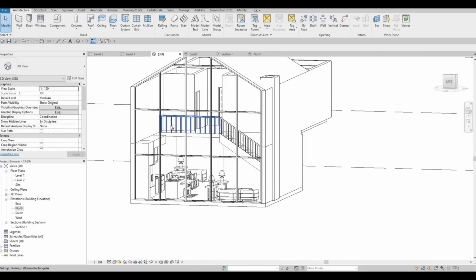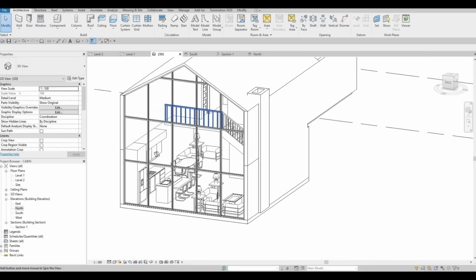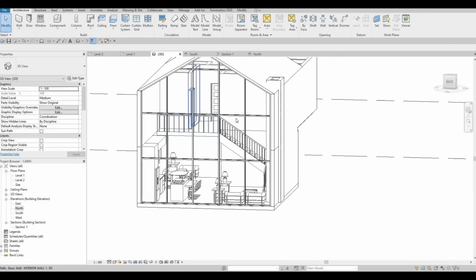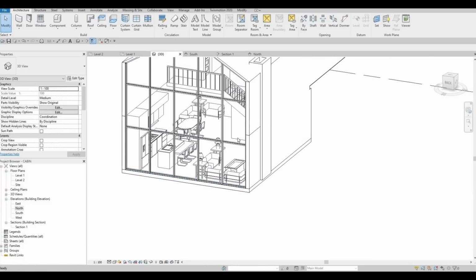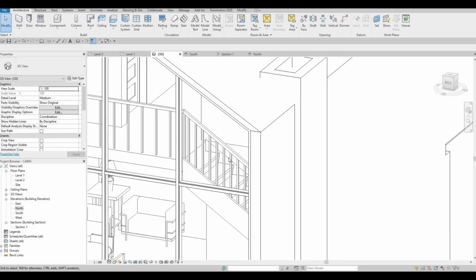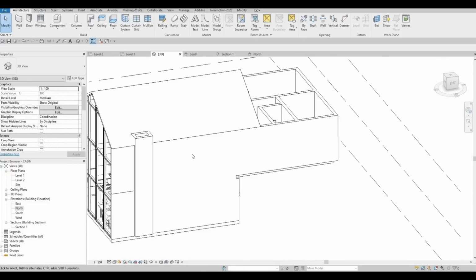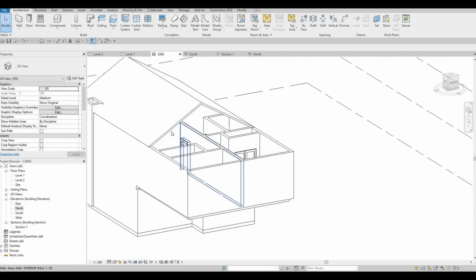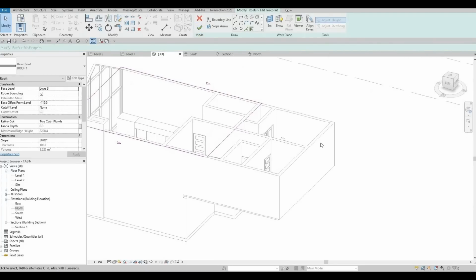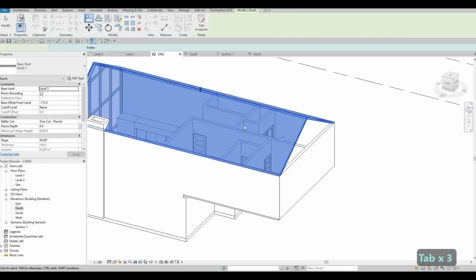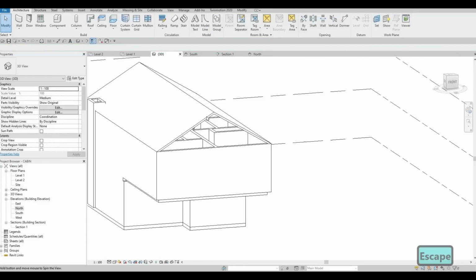So I'm just going to stick with 100. It's because of the slope, how the shape looks. That's why we need to change the thickness of this. And then here, we're gonna edit the footprint and we're gonna extend it all the way right here. So I'm gonna do a line and then a line here. Click finish. It will be aligned there.